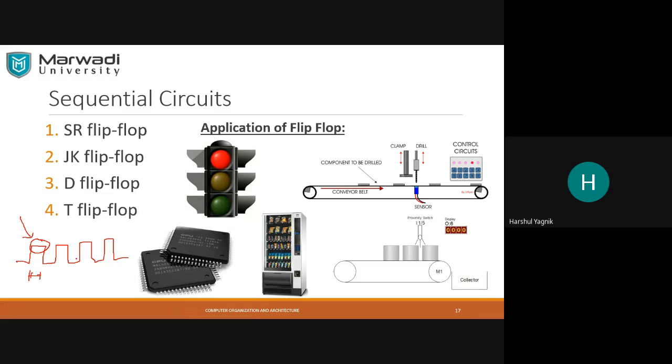Okay. Similarly, there are other types of triggering also, like logic 0 level triggering. So in that case, the flip-flop will update its value when the clock signal is logic 0, in this time duration only. Then, now most of the times flip-flops are not level triggered. Remember this. Latches are level triggered, but flip-flops are not level triggered.